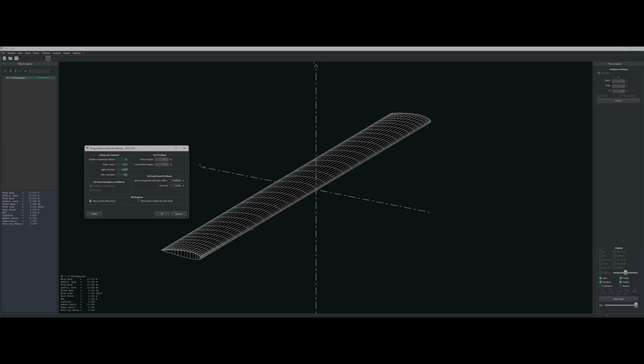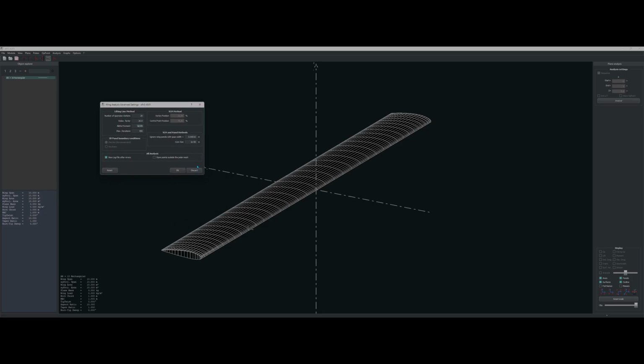So you want to keep these at a lower number. If you have it a little bit too high of a number, then it will converge very quickly, and you're going to get pretty inaccurate results. These are the settings I run: just 400 iterations, 1e-5 on alpha precision, and these two I just left alone. If you do an analysis and then find that your result is wrong, you might want to play with this a little bit.